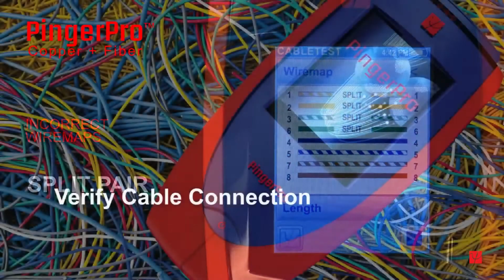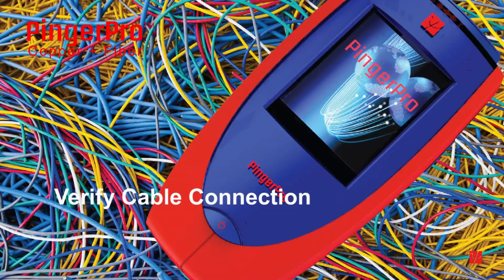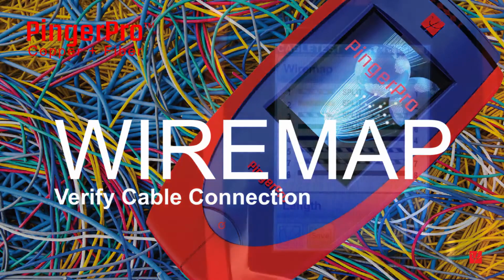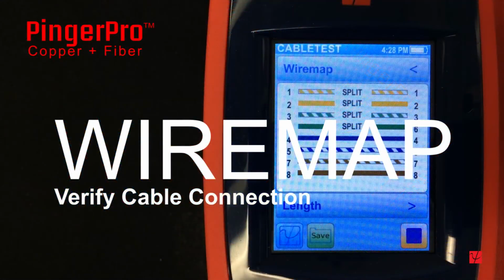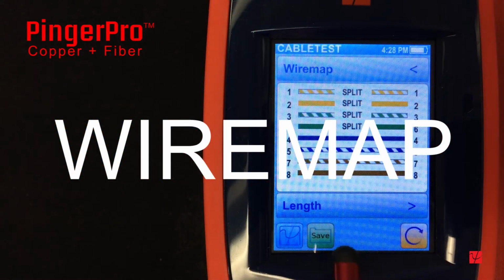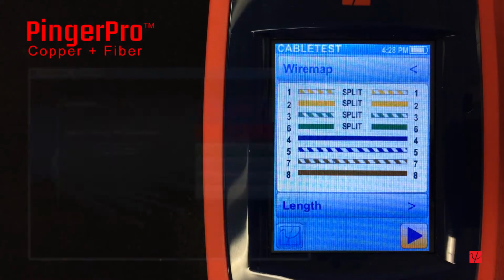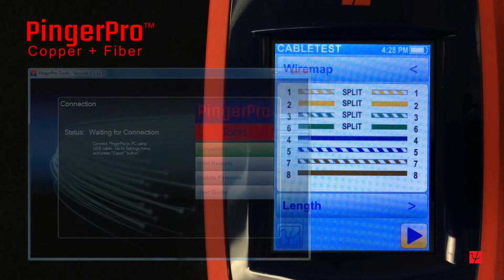Verifying that a cable has been connected properly is a basic network task that can be accomplished easily with the WIREMAP feature of the PingerPro. When you have completed a WIREMAP test, press the Save button to store the data. The data can be recalled later for review or exported to the PingerPro tools to document the test results.